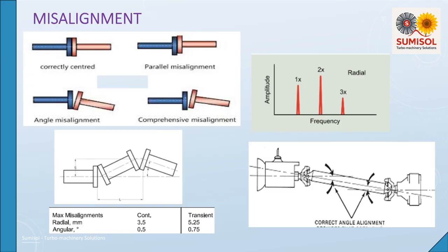For sliding the coupling spacer or tubular shaft, the location of the motor magnetic center must be known prior to starting the alignment. One should not assume that it is located in the middle of the total motor shaft axial travel.